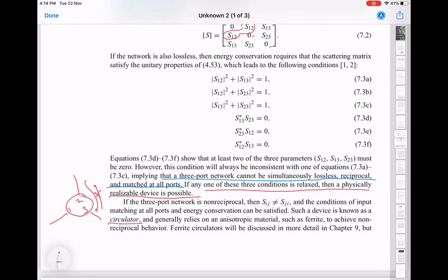There are active circuits, and in fact, this is a very strong field of research in the superconducting device community: how to build non-reciprocal circuits using superconducting circuits without using this magnetic stuff, because there is a fundamental problem that superconductivity and magnetism don't go well together. If you use these circulators, which are available, there are cryogenic versions of these things available. They always have a permanent magnet attached, and that stray magnetic field can actually affect your experiments. They tend to be bulky.